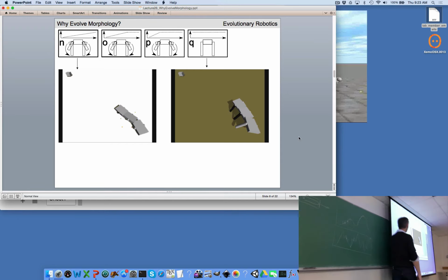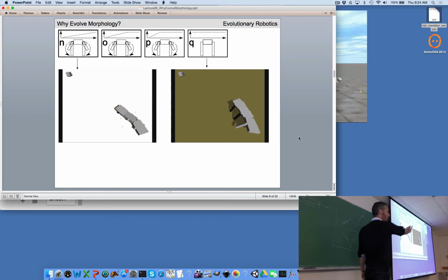Sure, right? This robot here reached the upright legged form in the last two thirds of its lifetime. So any controller, any neural network that managed to get this robot to the target object has some experience with successfully orchestrating the movement of these legs towards the target object, right? But it's slightly different because it hasn't had to do it over the entire length of the simulation. That's the whole point of Devo, the scaffolding. We're gradually removing the training wheels over evolutionary time.